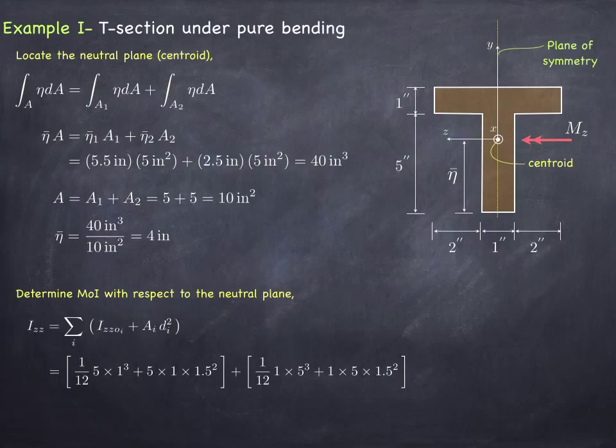For that, I will need first the second moment of area of that section relative to its own centroid, and that formula is simply the base length 5 times the height cubed, which is 1 cubed, divided by 12. That is a formula that you can derive by yourself for rectangular cross sections.